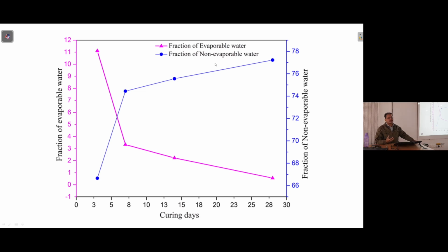Then what happens at the grain boundaries? You have mismatch. Similarly here, as the CSH gel formation takes place, it will grow in size at different locations after nucleation, and in between you will have some space which will not be filled, where the gel formation will not take place. There this water will tend to reside. So it is that location where you have this evaporable water content.